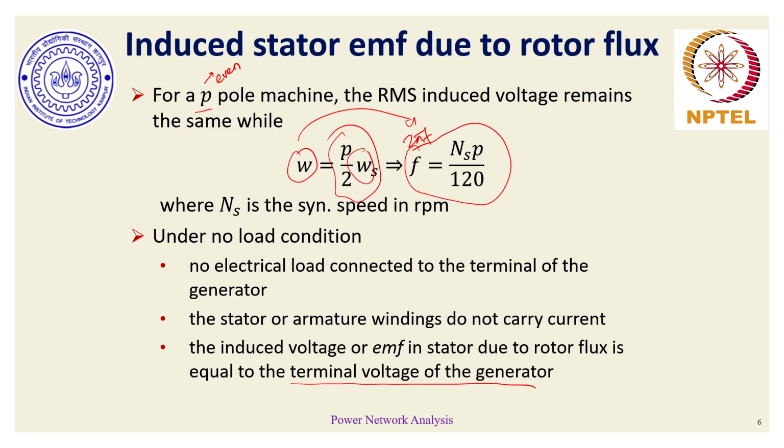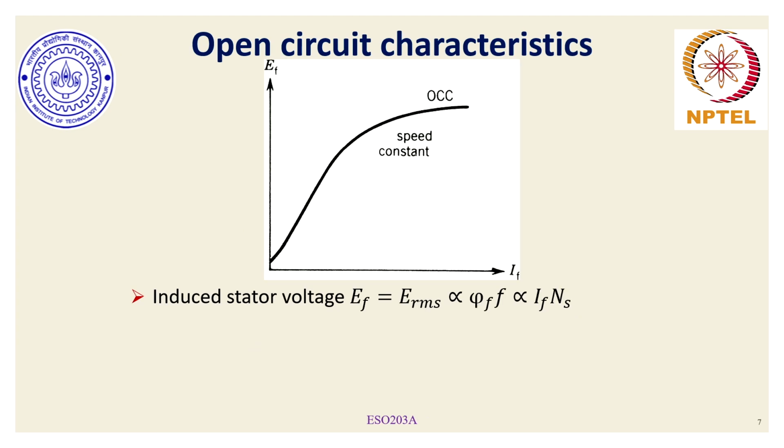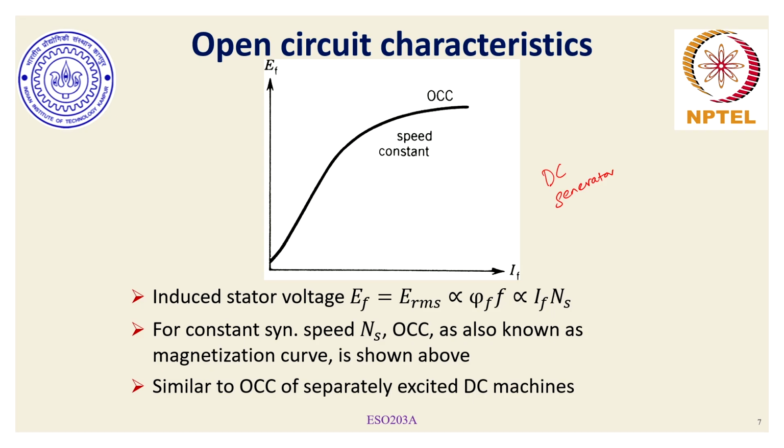There is no voltage drop in the stator windings or armature windings. However, to continue this discussion on induced EMF, if we were to plot the open circuit characteristic through some OCC experiment for a synchronous generator, this OCC is very similar to the characteristic also present for DC generators, which essentially says that the induced EMF is proportional to the field current.